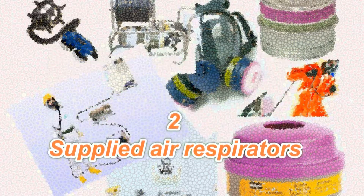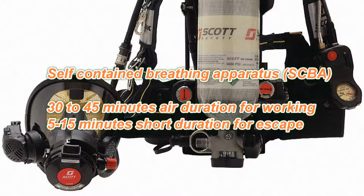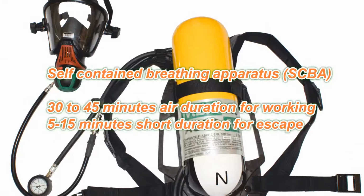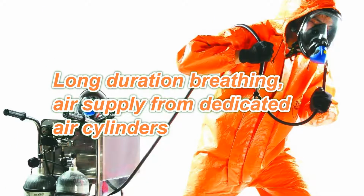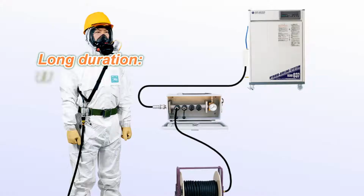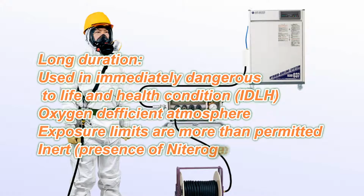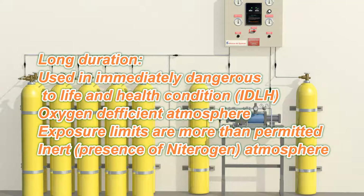Supplied air respirators, using breathable air in a closed system, come in different capacities and durations. Some have a self-contained air cylinder with a limited supply of air worn by the worker, and others take air from outside the working area from dedicated air cylinders, which are usually for long working durations. Supplied air respirators are used in areas where inhalable agents exceed permissible exposure limits, where there is a deficiency of oxygen or presence of inert gas such as nitrogen, or any other chemical vapors, smoke, or gas that can be immediately dangerous to life and health.